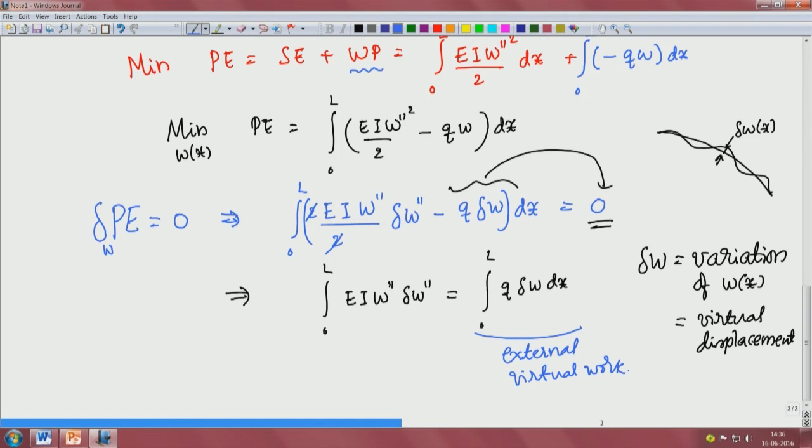Okay. So, what we are saying is that somebody says that for a straight beam, this is the equilibrium deformation under some loading q of x, and we want to verify, is it really? We go back to the principle of minimum potential energy and imagine a virtual displacement as if it is perturbed. When it is perturbed, to first order it should be equal to 0.